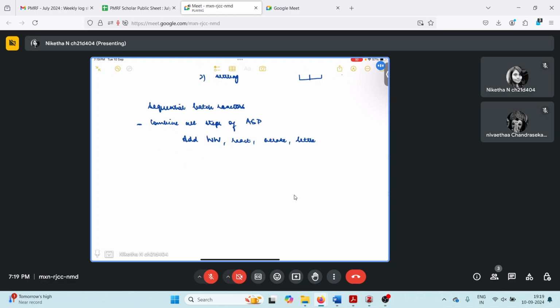So in one tank, if you want to do all these processes, then you have to do it as a sequence, right? So first we have to do equalization, and then we have to do aeration, and then clarification or settling in the settling tank.